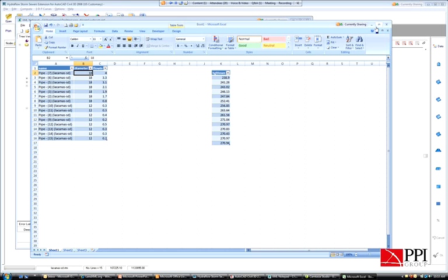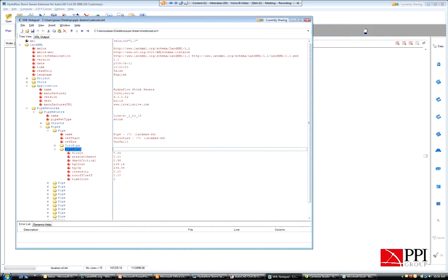And so what we went over here today was you can use custom expressions to affect your label styles. Within some of that, you can bring in some relatively simple hydraulic equations, also some hydrology, which I didn't get into, but you can imagine you could show that also in your watersheds, create watershed tables, do simple rational method stuff within there. It's not going to be the end all, but it can be a good preliminary design tool in terms of those things.